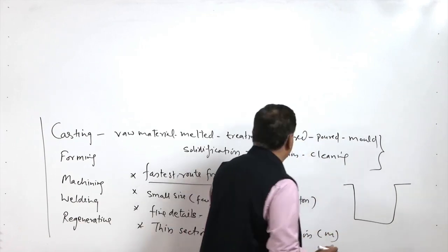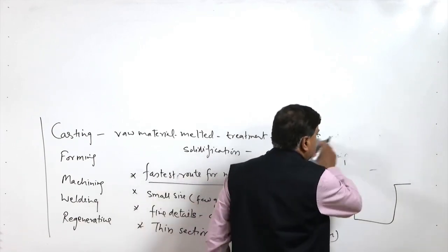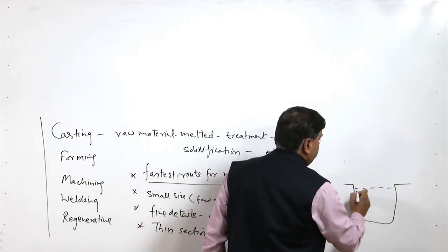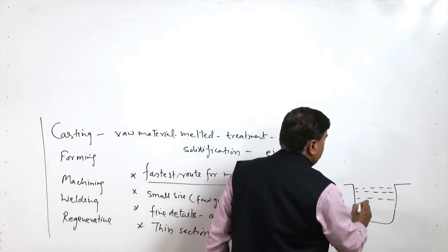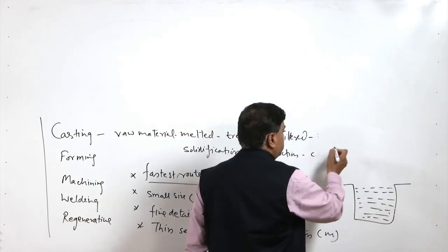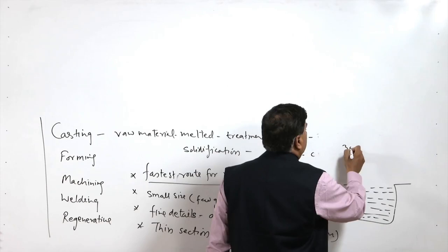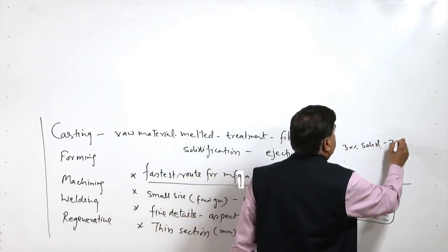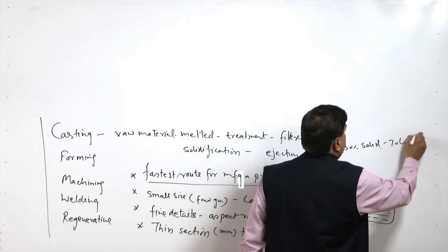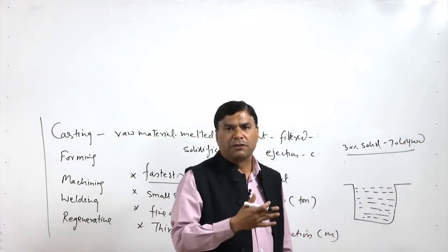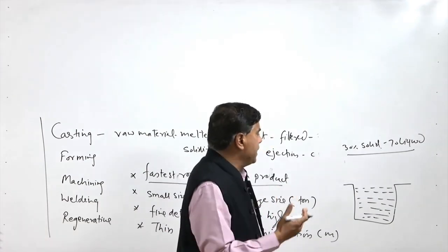So, in this method, basically the molten metal is maintained at a correct temperature, so that there is a mushy zone wherein, say, 30% solid and 70% liquid. This is the two phase zone state which is normally used, like 20 to 30 or 40% solid and the remaining liquid.